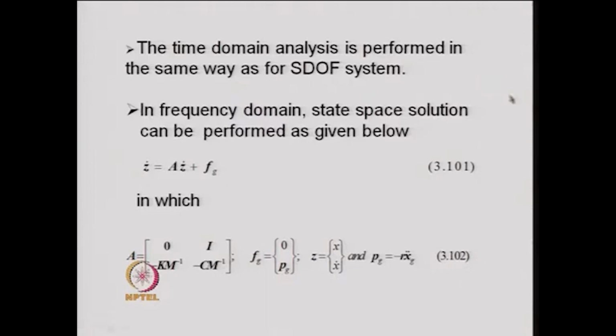But for a multi degree of freedom system, generally we are not able to solve the problem using Duhamel integration. Therefore, we generally do not try to solve it using Duhamel integration for a multi degree of freedom system in the state space form. In that case we generally use some other integration scheme than the Duhamel integration.